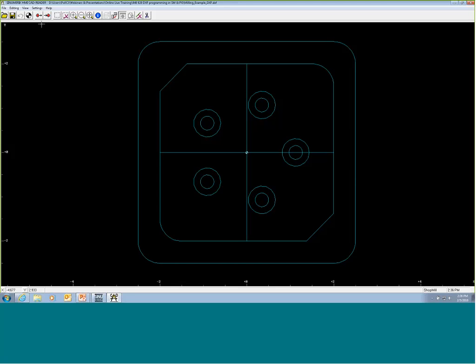So from there, you have your two buttons, the start and the end point. So you're always going to obviously want to start with the start point. And just like in moving the zero around, we have a couple different ways to pick entities. So I can pick the center of an element, and again, an elemental line or arc, any feature. I can pick the start or an end point, and it'll be specific to my position of my mouse, or I can just click with the mouse and it'll try to start there. So in this case, I'm going to pick the start endpoint feature.